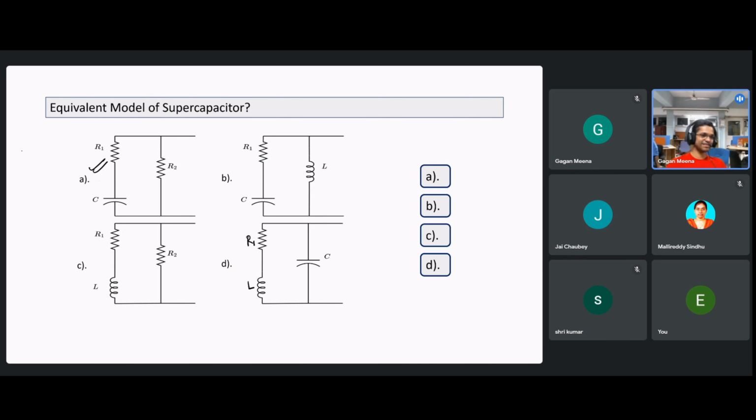This is the basic principle of supercapacitors. We know that Q is CV, and C is epsilon A by D. If we want to increase the capacitance, what can we do? We can change this epsilon, which is epsilon naught into epsilon R. Either we increase the dielectric strength, or we increase the area, or we reduce D. Reducing the gap beyond a certain point is very difficult.